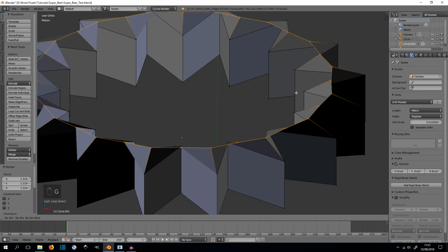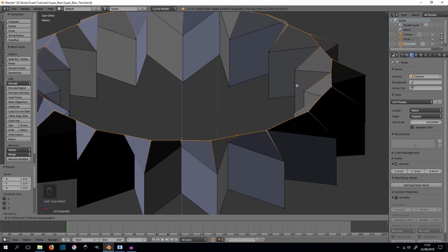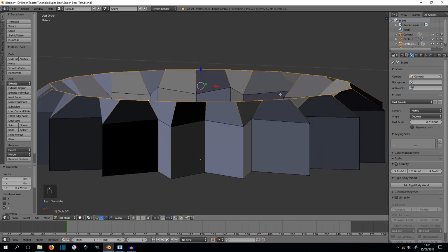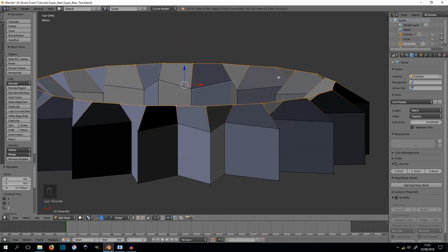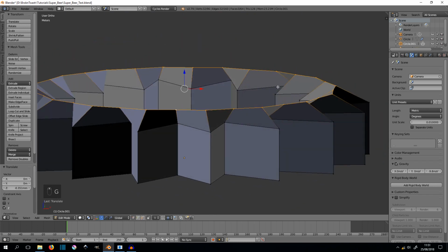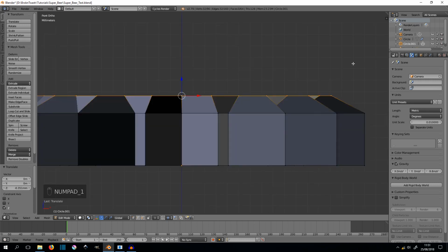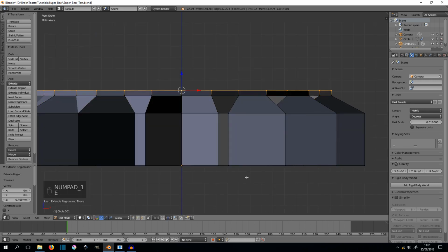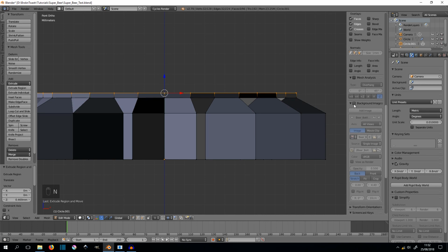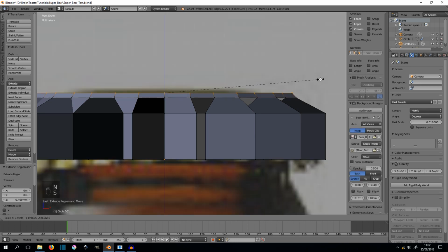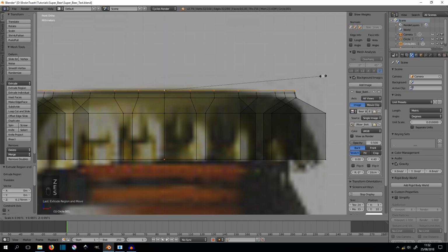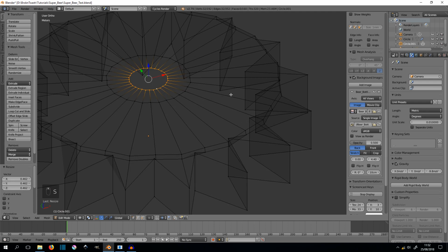I will select everything. I will create a small displacement like so. That can be a bit down again. I shall extrude it, and now I will put the image again so I'm aware of the overall size, and I will start closing this shape and then close it pressing F.